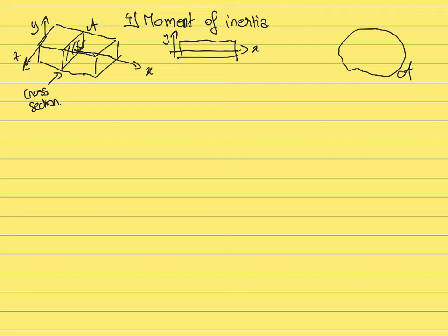So the first thing that you can define is the area of the cross-section. When you have a surface like this, the first geometrical property that matters is the area of this surface A. So if you want to calculate this area, what you will do is take every point M of this surface. For every point M, you will define an infinitesimal surface dA, where in this case, dA will be equal to a small variation of the y-axis times a small variation of the z-axis.